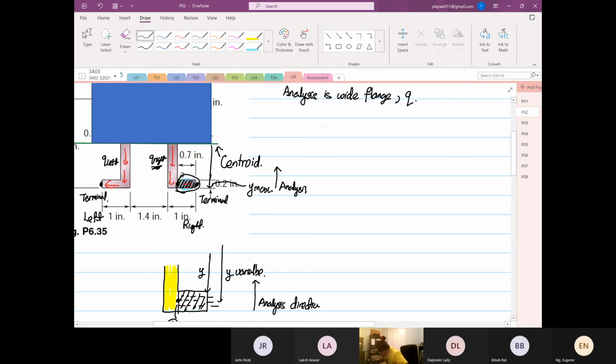So the shear stress at point A is equal to Vy over Izz, and then Qz divided by t.